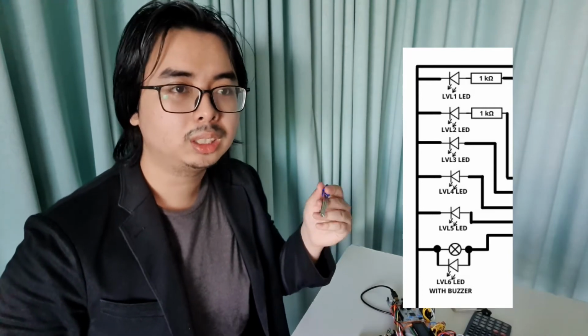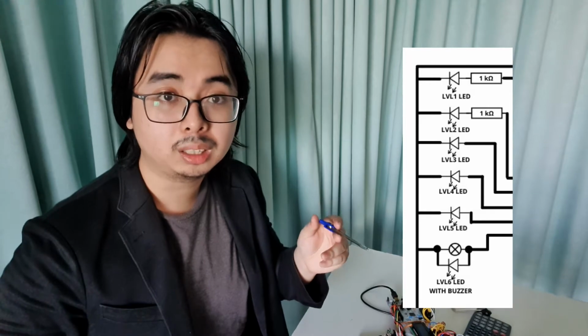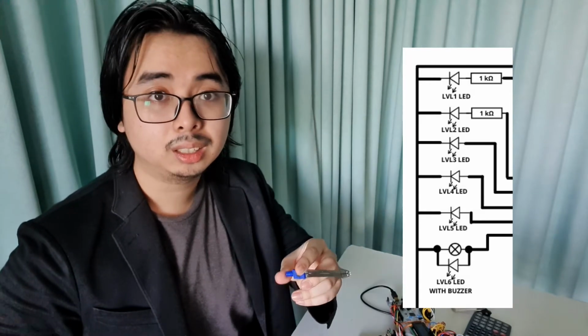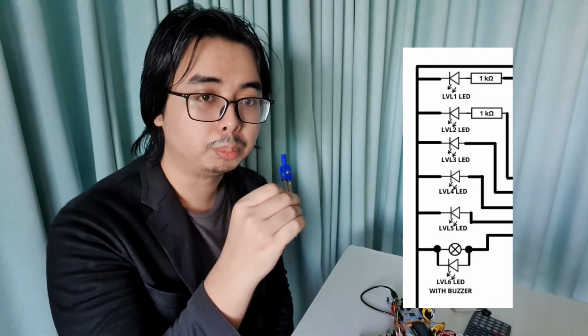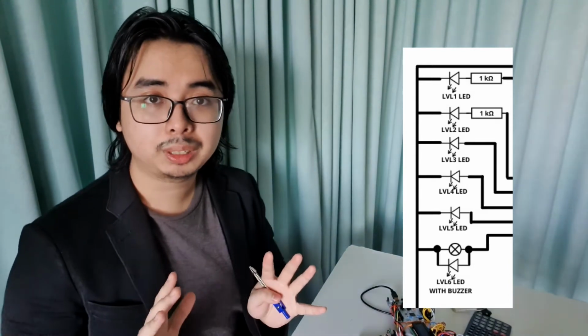Now as we know, using KVL, for a buzzer connected in parallel to an LED, the voltage is distributed equally. So when the value of the current temperature hits the user input temperature, it will alert the user with a sound. The same goes for humidity. So we have already explained the fundamentals of this project. Let's design the circuit.